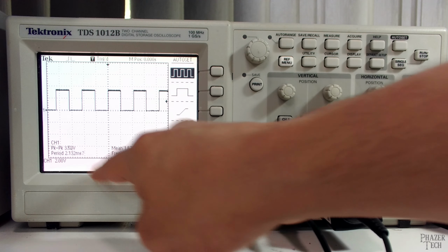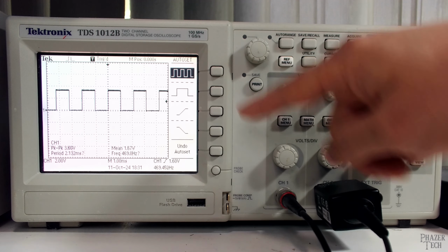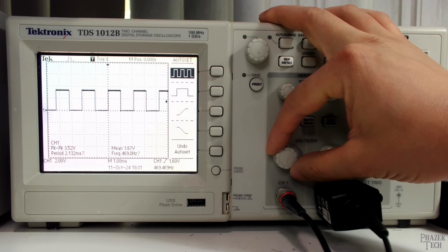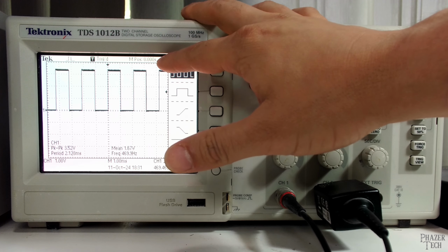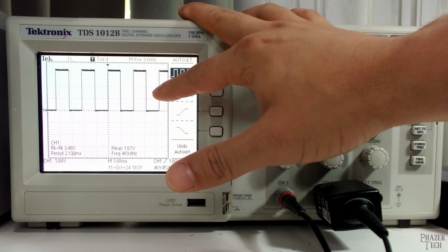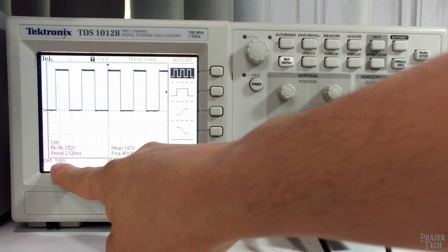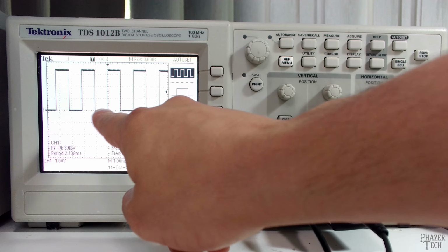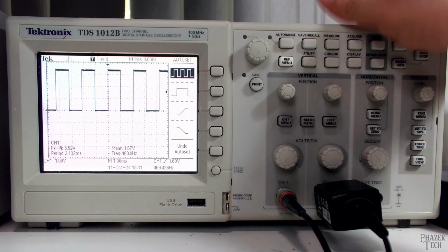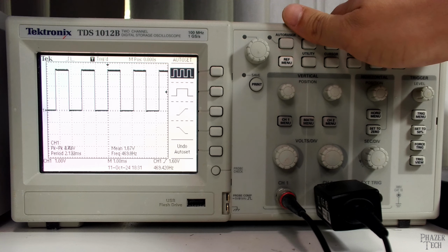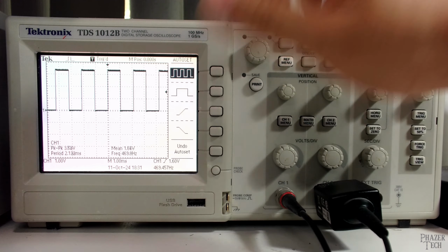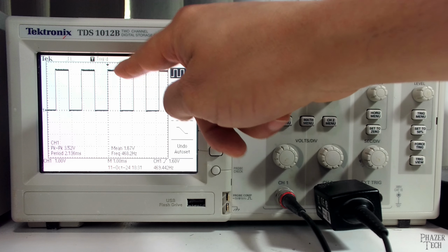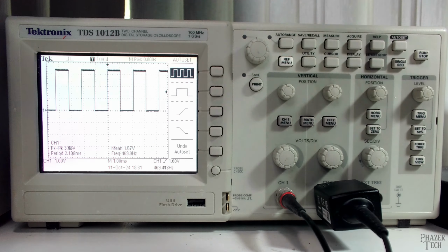So when we adjust the vertical position here, we're adjusting the y-axis value. So I'm going to turn this clockwise, and we can see that the height of the signal jumped up. So now down here you see channel 1 equals 1 volt. So now each square in the y-axis represents 1 volt. And the Raspberry Pi outputs 3.3 volts. So this makes sense. 1, 2, 3, a little over 3 volts is what this is telling us.